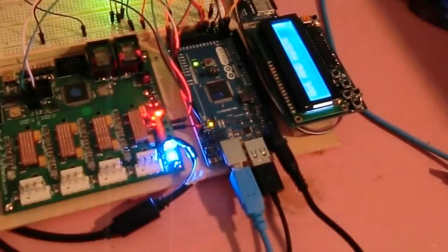In addition to the straight G code settings, we've got a few different relay controls, and so far I have two toggles here, one for air, and another to insert and retract the mold. And so that would also generate program instructions. They wouldn't be G-code program instructions, but they would be program instructions to the ADK board to trigger the appropriate relay at the appropriate time.